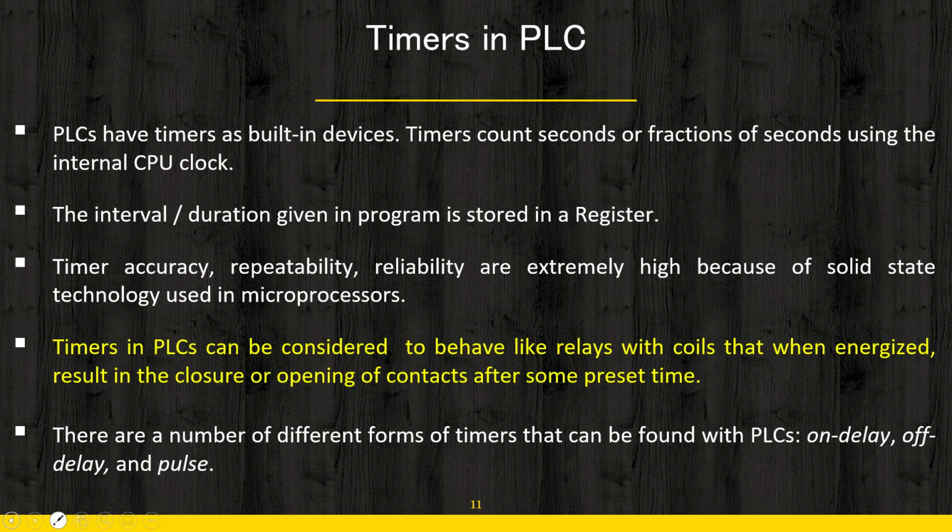Now the time interval and duration, whatever we feed in the program, is stored in a register. Here you see that even with timers there is the concept of a register. As I have already shown you in the register section, there is a holding register, and the purpose of the holding register is to hold the time that we have fed.